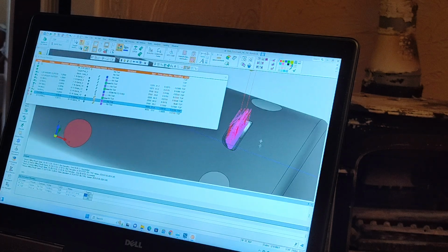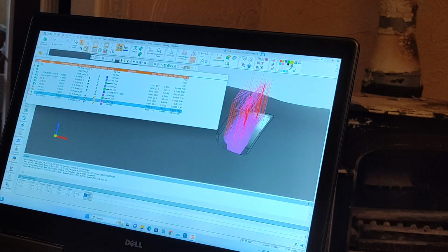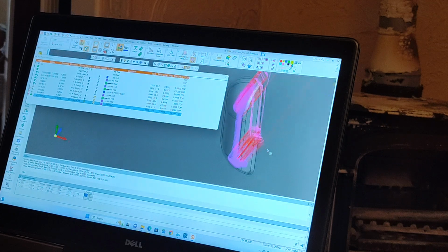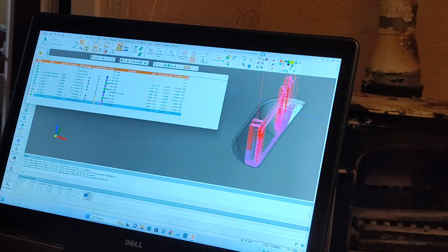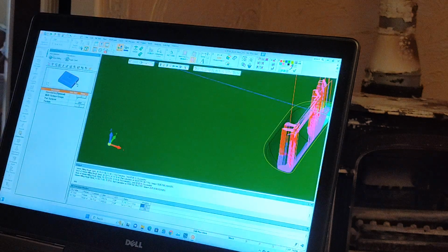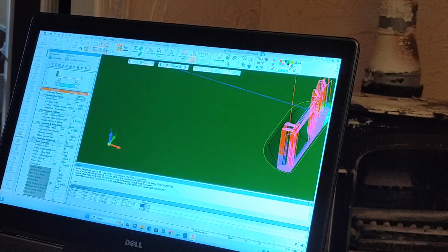Okay, here's our roughing path with the 1/16 ball, and then the roughing path with the 1/32, and then we'll do a copy and paste and change this to finish procedure, finish mill by limit angle. And we just have to change the side step.